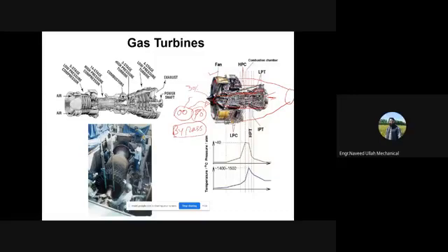Okay, it is not taking part in this conventional gas turbine process. It is just bypassed. Okay, and due to this, it comes here and it is mixed with the exhaust. And if you look at this shape, okay, this is basically a nozzle. So just by introducing the idea of this nozzle shape, this exhaust plus the bypassed air that are actually here, it is leaving the nozzle with high speed, and the jet velocity is more. Or the jet is leaving this nozzle with higher velocity, and as a result and as a reaction, a thrust will be produced in the forward direction.